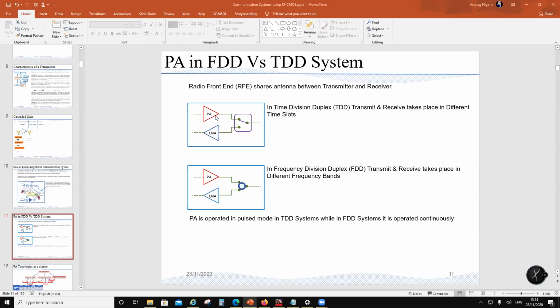It has to tolerate a very high VSWR, 8 or 9:1, or people go up to 20:1 VSWR in a non-destructive case. Performance is at about 2:1, so you have to guarantee performance at 2:1 VSWR, for example, and ruggedness up to 20:1 VSWR, with hot and cold cycles and so on.